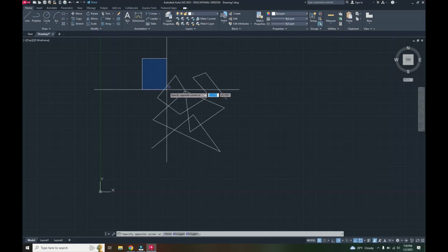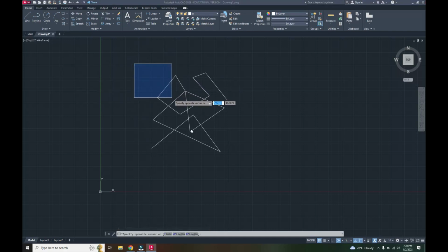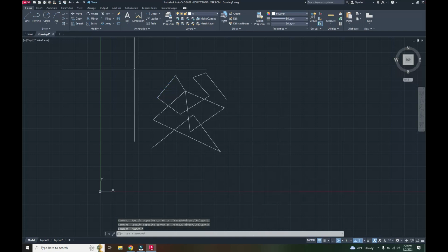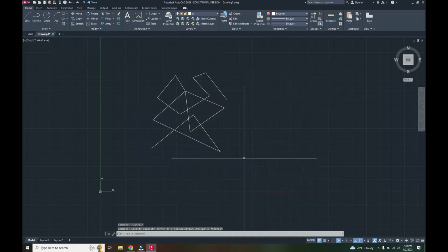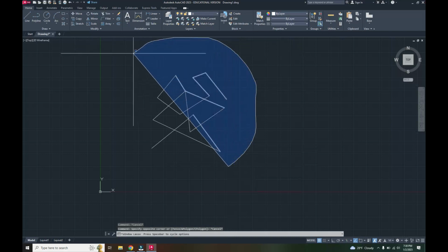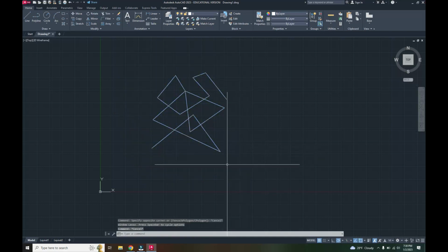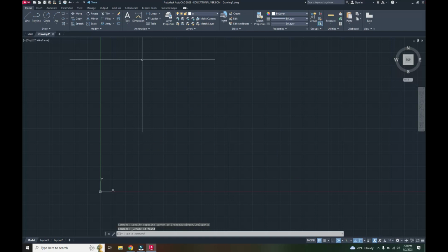Now if I go from the upper right or upper left and I drag to the right with blue, you can see what happens here. It's not selecting the line the same as it did with the green. But if I go over the entire line, like so, you can see it selects it. So that's the difference between dragging from the lower right and the upper left. You can also do a lasso going around it if you want to. Okay, so I'm going to click from the lower right and go back up, and I'm going to delete.